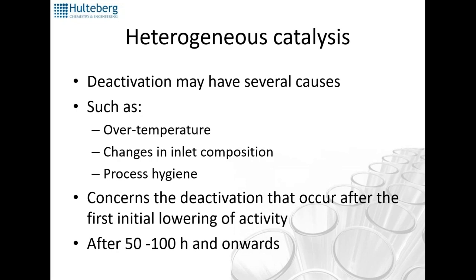Another important thing is process hygiene. So how well is the upstream cleaning operations being done? And this is concerning the deactivation that occurred after the first initial lowering of activity. When you have a fresh catalyst, you have a certain activity, but it sort of settles in and drops down to an unstable activity after maybe 50 to 100 hours. So deactivation to me is something that happens after these 50 to 100 hours.